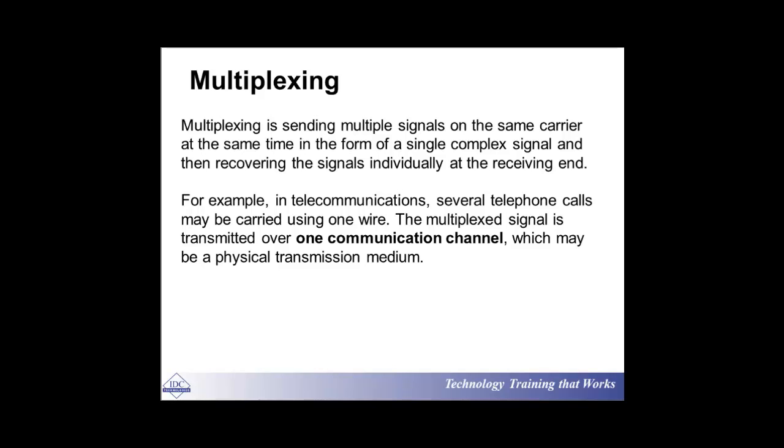So in these cases, what we do is that we calculate the maximum bandwidth of the channel, and we just divide it into a number of slots, okay? And then we put the signals next to each other, so they will sit next to each other within the bandwidth of the channel, and basically that is what we understand by multiplexing. So this is how multiplexing works.